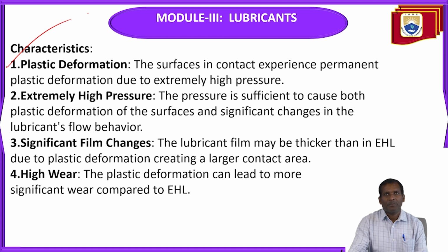Plastic deformation. The surfaces in contact experience permanent plastic deformation due to extremely high pressure. The extremely high pressure means the pressure is sufficient to cause both plastic deformation of the surfaces and significant changes in the lubricant's flow behavior.